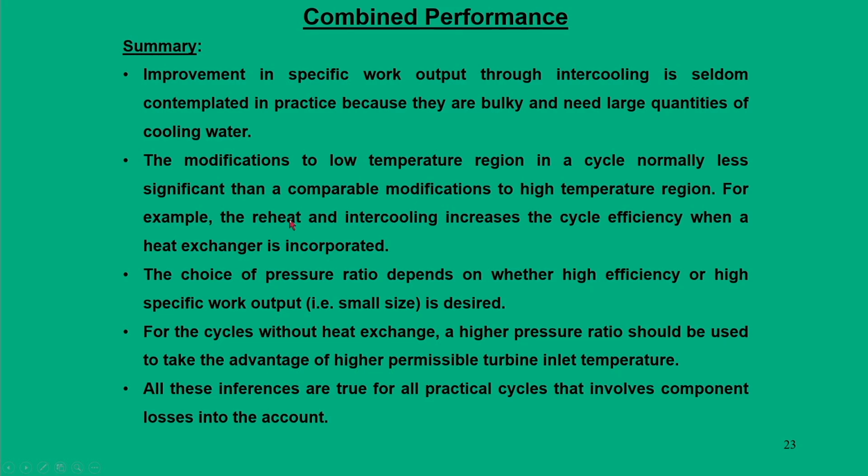You would be getting intercooling unnecessarily, because the low pressure gas does not have sufficient work capacity or heat capacity. So, there is no point in going for significant modification. Modifications are treated only in the high temperature region of the cycle. So, reheat is a better approach than intercooling, first thing.